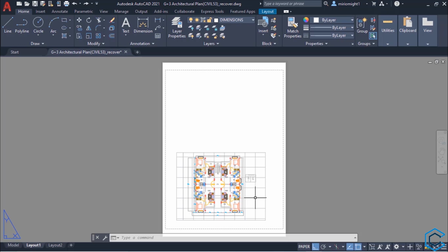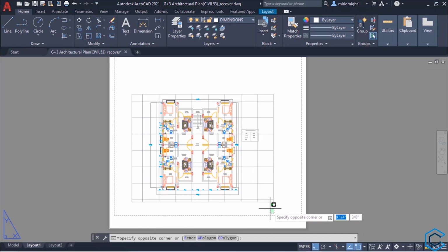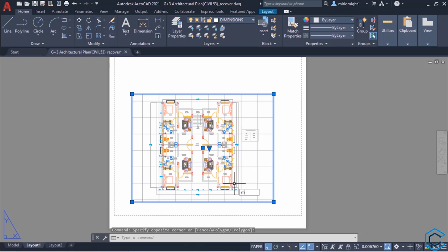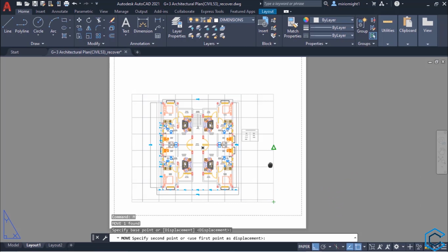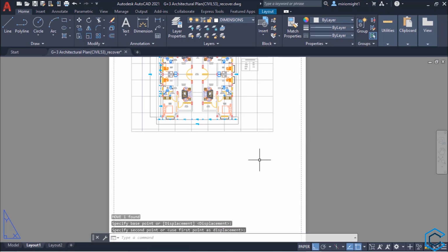This title block will act as a marketing template for the design firm, as these sheets are viewed by a number of people on site. On A3 paper, we provide the title block in the lower part of a sheet, so let's start drawing the title block. Move this model box like this to the top. Draw a line like this.